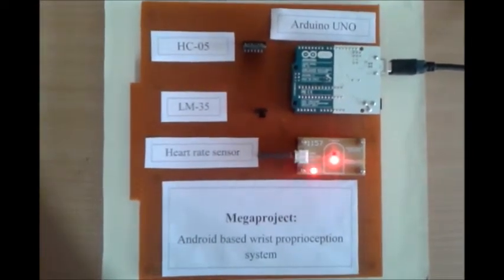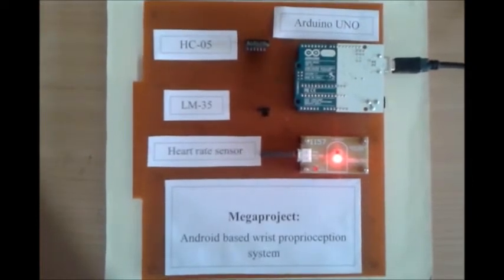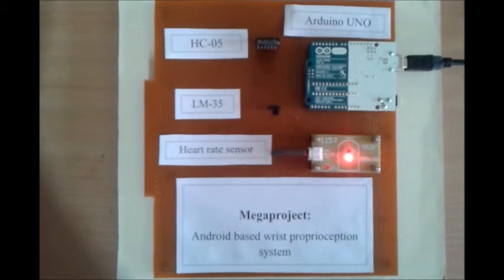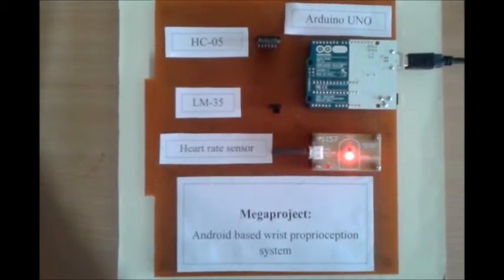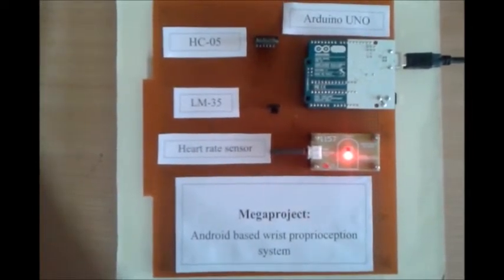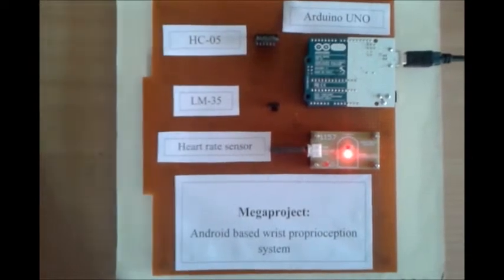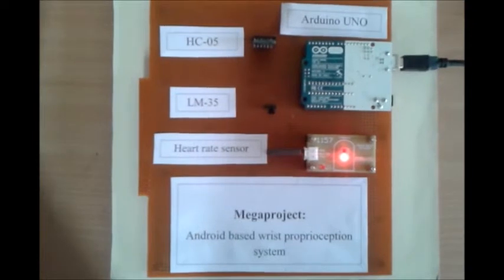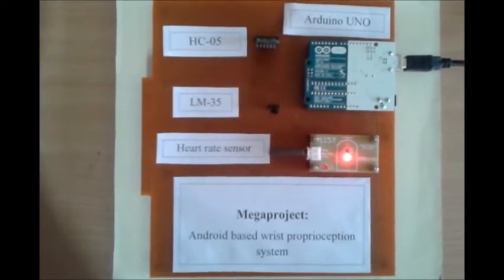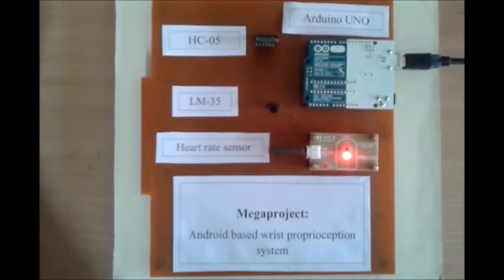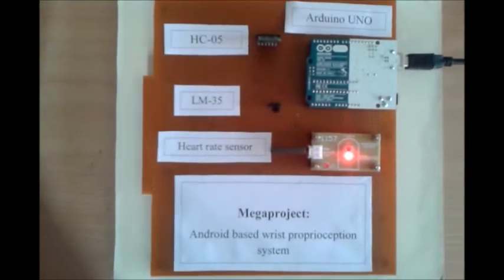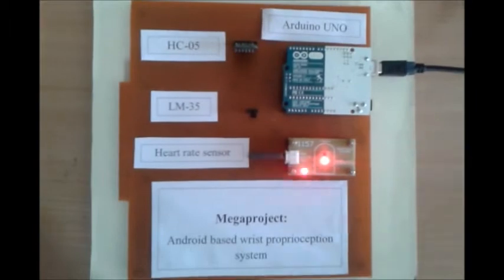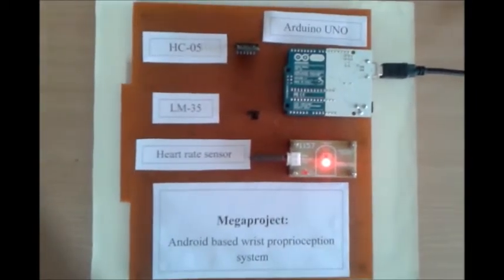The heart rate sensor depends on the principle of light modulation by blood flow through the finger at each pulse. Oxygen in blood absorbs the IR rays, so the reflection of IR rays varies. The sensor gives an inverting output and produces a TTL output. This data is gathered in analog pins of Arduino. Pin 0 of Arduino is assigned for the pulse sensor and pin 5 of the Arduino is assigned for the temperature sensor. The raw data is processed in Arduino.